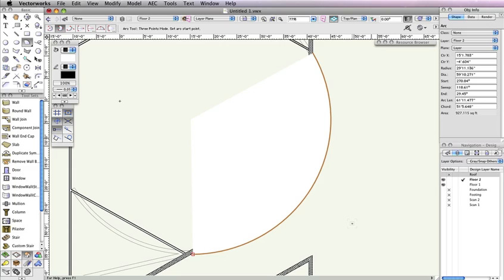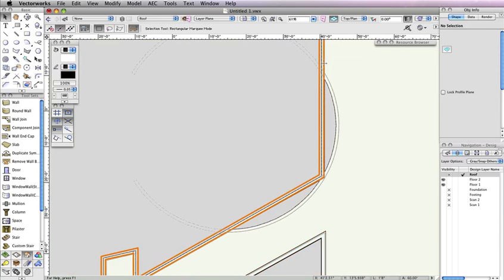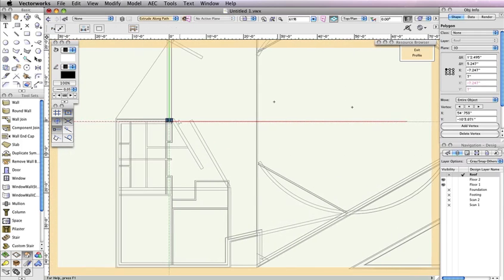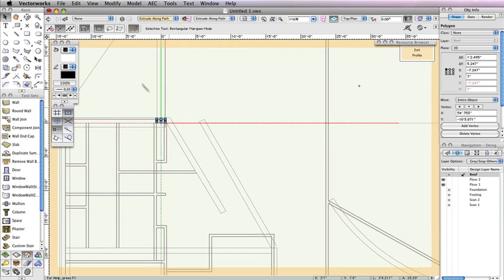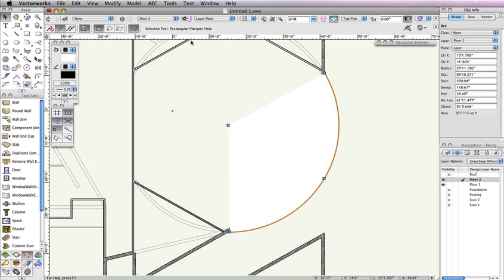To create the flashing cap, you're going to repeat the steps you used to create the triangular walls flashing cap. For the moment, set the roof design layer as the active layer from the view bar. Next, switch to the Selection tool. Double-click the Extrude Along Path and choose to edit the profile. With the polygon selected, go to Edit, Copy, then click Exit Profile. Switch Floor 2 back to the active layer and go to Edit, Paste.